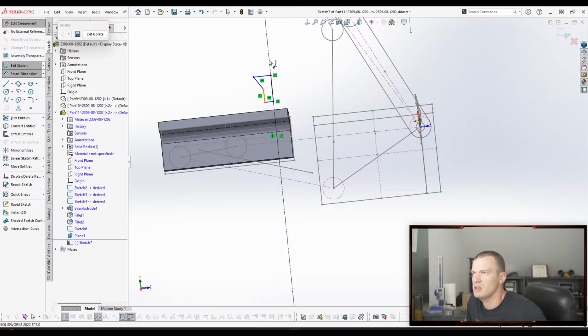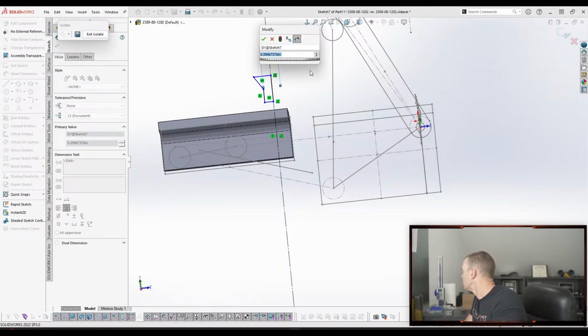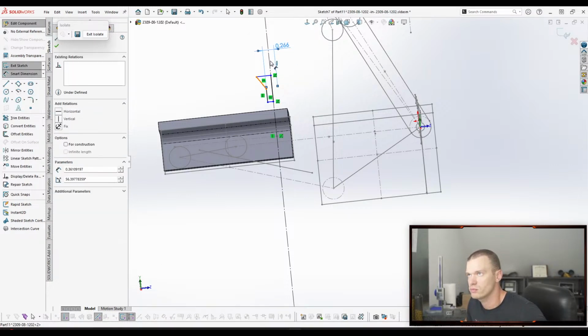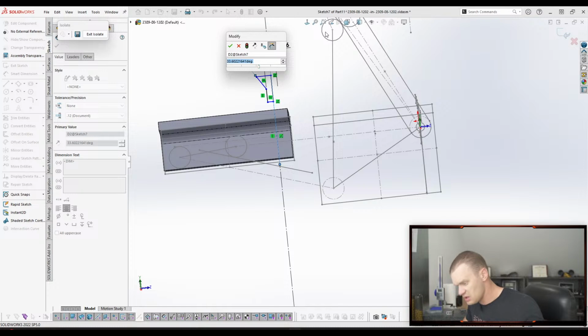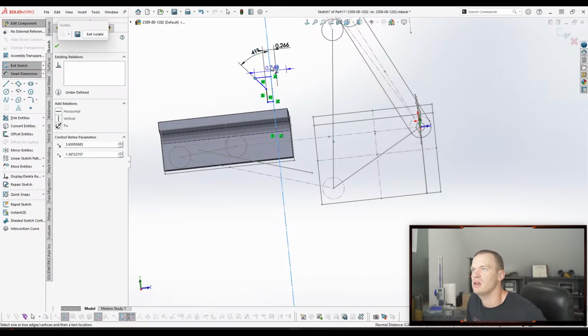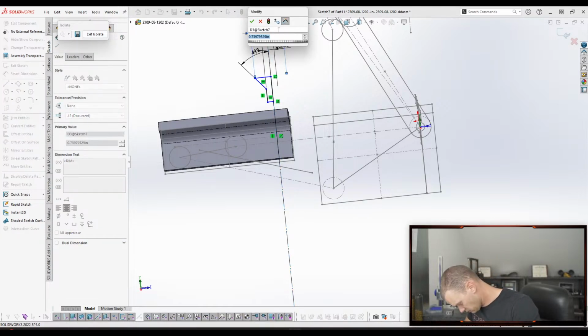So we know that it is a 10-24 screw, but they're putting in a clearance hole for a 1/4-20. All right, and according to my chart here, we should do it 82 degrees. And the head diameter on a number 10 is .385.